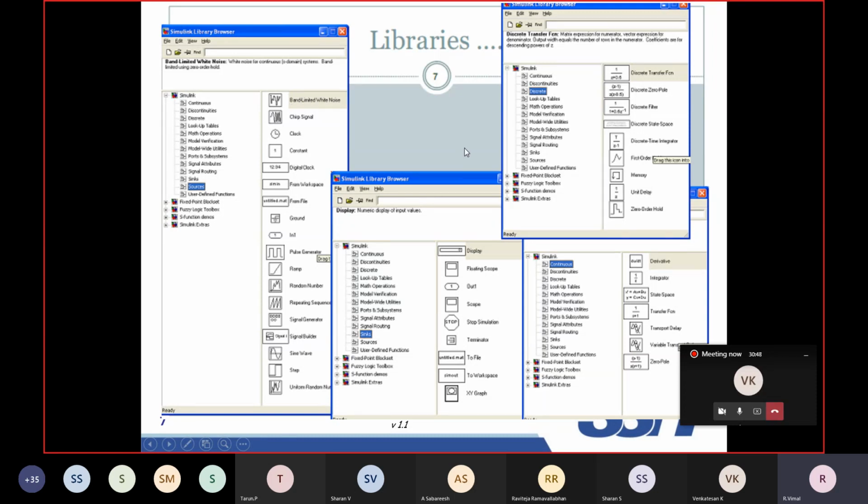If you want a time delay to be set into the model system that you are developing, select clock and pull it into the workspace. If you look at sinks, and sources: the source is the initial first stage. All the element boxes listed in source we'll use as the stage one, first element, and all the elements displayed in the sinks will be the final one. Display, scope, out. This will be the final one.